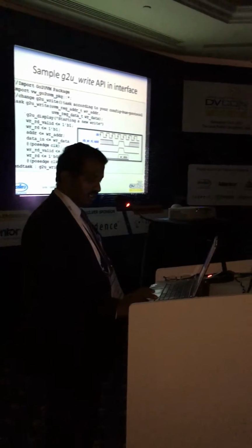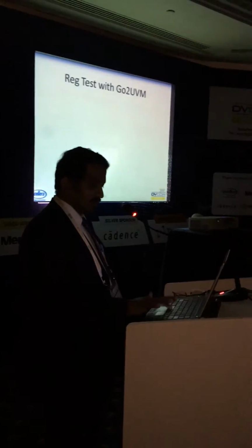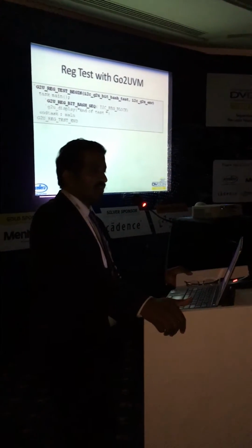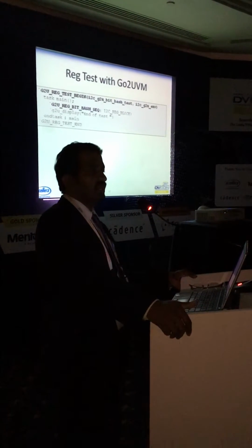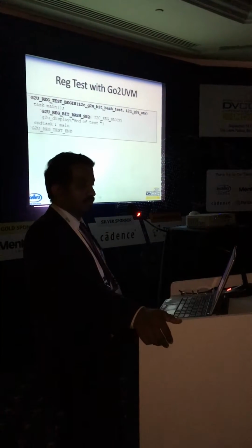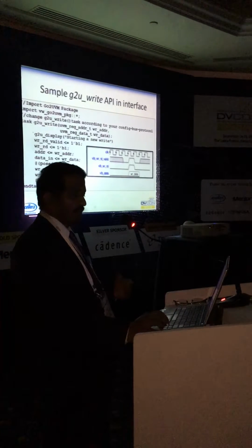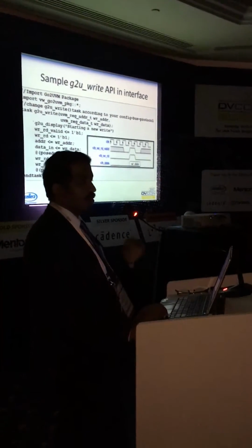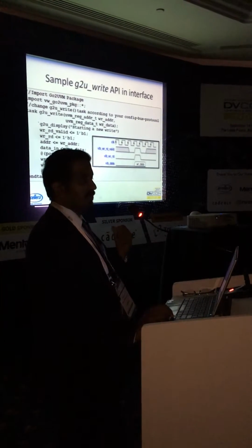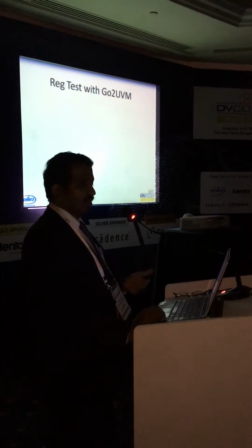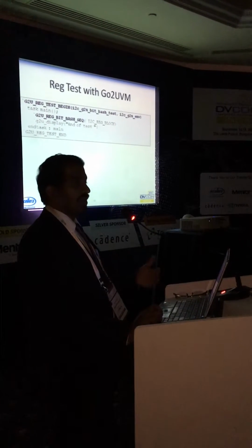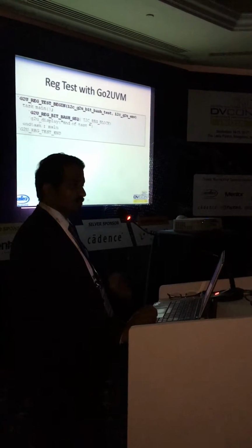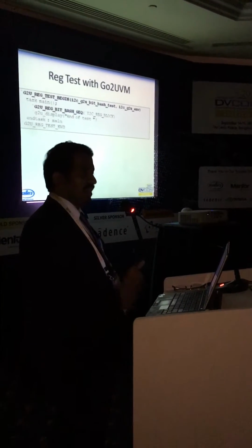The moment you do that, let's see what we can do with this. Let's look at the test. This is the beauty of this. If I have a design with, let's say, 50 registers, you generate your UVM register model, push a button, then you fill in the one I showed you previously, and you're up and running. All those 50 registers can be tested on day 1, if you can write this in 1 day, which I believe we can. You write this, then we can actually start running real tests with UVM. You do not have to be an expert in UVM to start using this. It's all you need. And some of this we actually generate using the app as well.